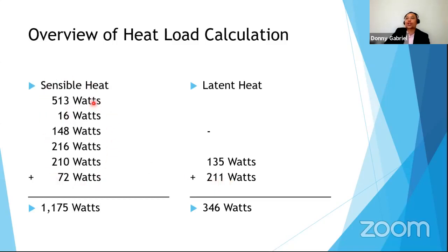Total sensible heat load. Yung radiant natin, yung conductive natin, yung equipment natin, yung lighting natin, and this is the occupancy, yung mga tao, and this is our outdoor air. So mapapansin nyo, doon sa equipment natin, wala tayong latent heat. Doon sa table, walang nakalagay na latent heat load. There's no latent heat load for the equipment. Sometimes there are equipments that produce latent heat load, but in our case, the plotters and the computers don't have a latent heat load. So that's why our latent heat load here is 0.